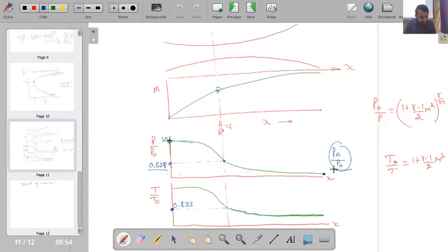So what I am saying is that, say PE is the pressure which was required to, I am calling this as PE. So PE is the pressure which is required to maintain Mach number equal to 1 at the throat, or I can say at A by A star equal to 1. Okay, this is the pressure PE. But if my pressure difference between starting and exit is not equal to PE and it is other than PE, then what will be happening? That is something which I actually want to determine.